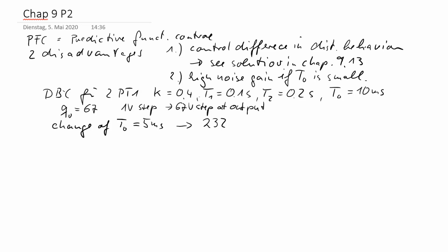Noise on the actuator output could produce a very big loss of energy or heating of the actuator and motor and so on. So if you want small time constants, this gain leads to a high load on your actuator. A short demonstration should show you what I mean.